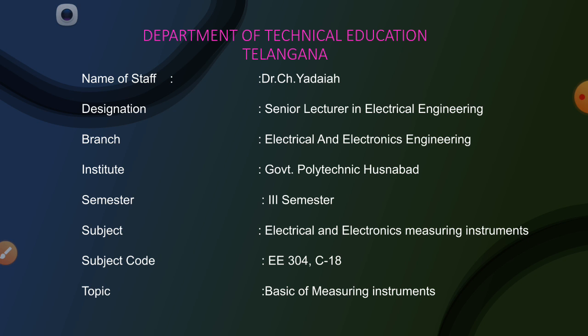But the gravity control instrument is very robust and cheap, whereas spring control meters are very delicate and costly, but can be used anywhere. It is portable and gives accurate readings, whereas gravity control is preferred for panel mounting only, and the reading may not be accurate. These are the differences we discussed in the last class.